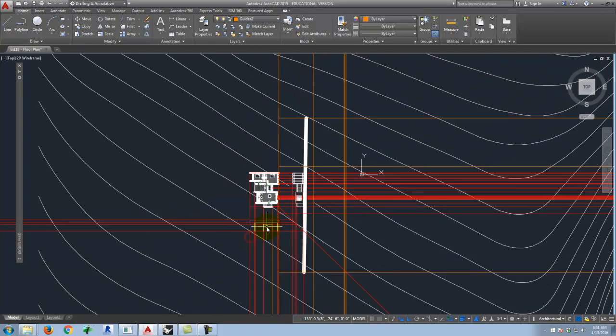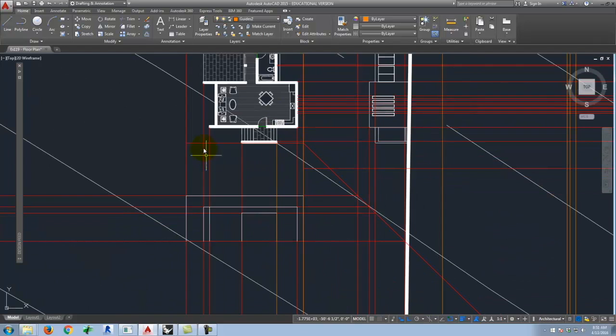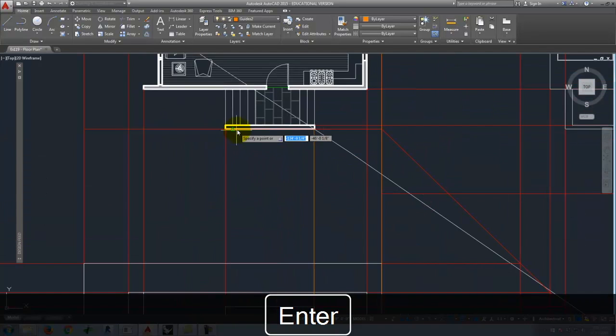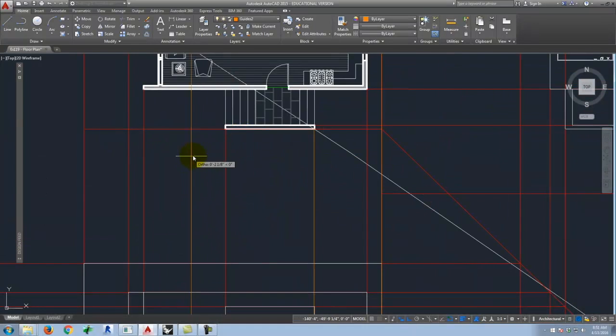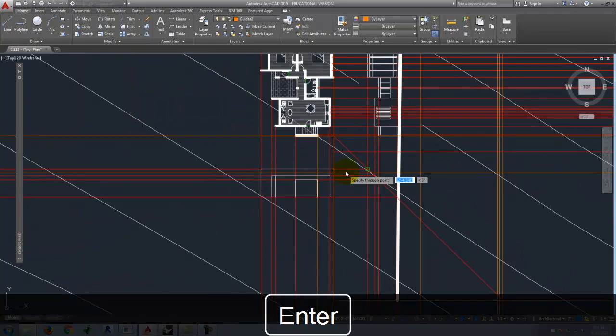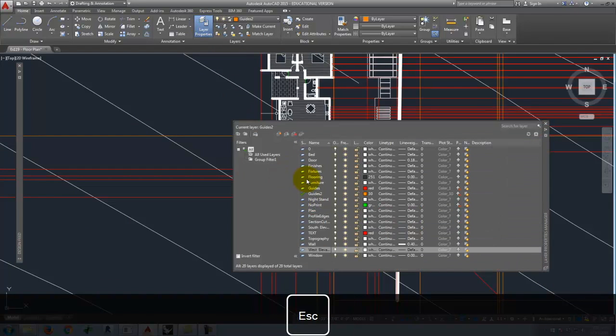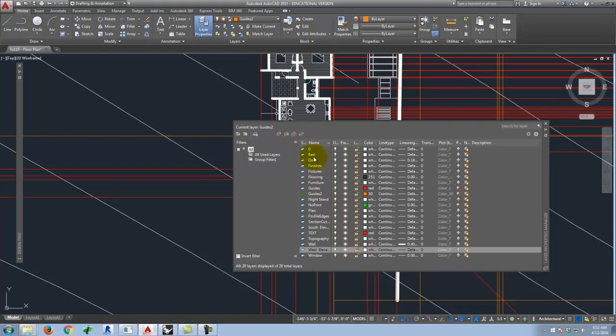And so once again, if I look at this bounding box, I want to extend a construction line in both directions. So I'll say X line, which is just a ray that goes in 2 directions. And this time, I want it to go through this point. So now I have a line that's going in this direction. Actually, you know what? Let me make a Guides 3 layer so you can see the difference in the colors, because it starts to get too confusing.